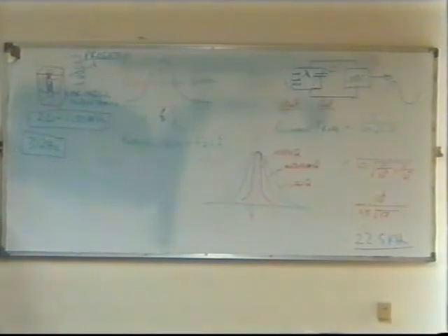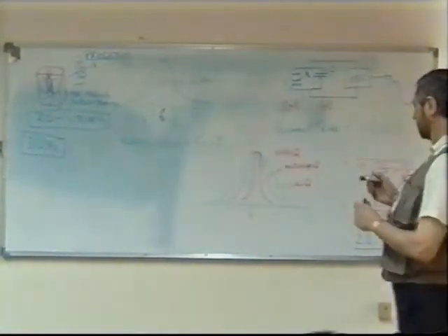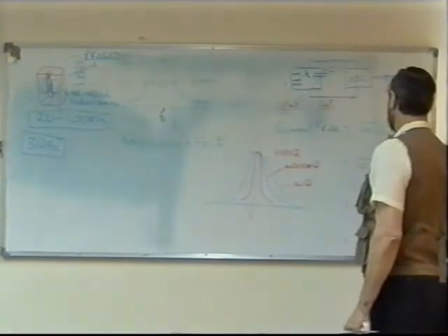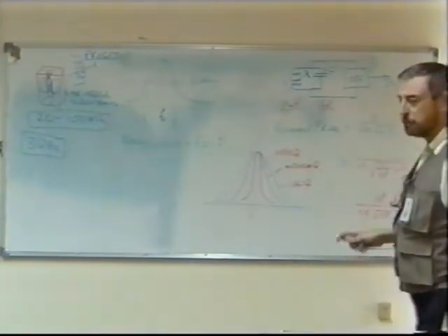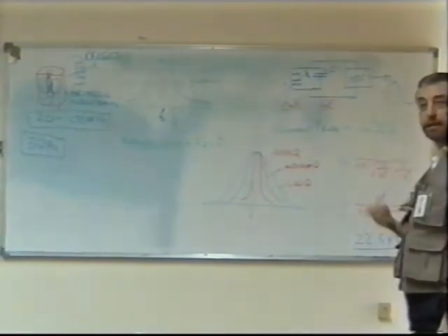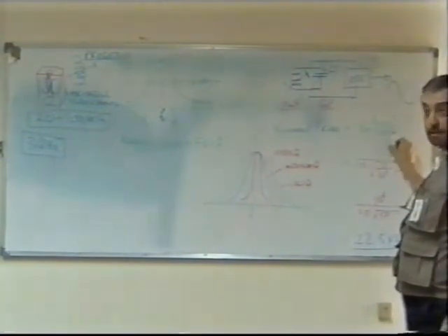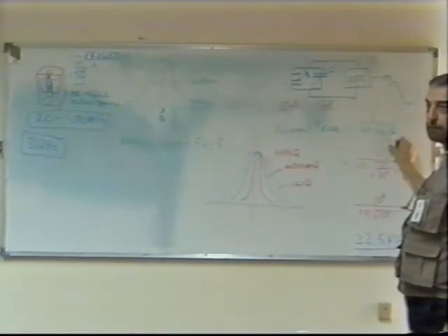In fact, you could get a piece of wire no longer than that, which would be sufficient inductance to give you the necessary circuit for resonance. If we have a look at this formula here, this gives me the resonant frequency, agreed? But if you look at this formula, there's no fixed value of L or C that will give you that resonant frequency. If I change the value of L, you can change the value of C to maintain the same resonant frequency. Isn't that right?